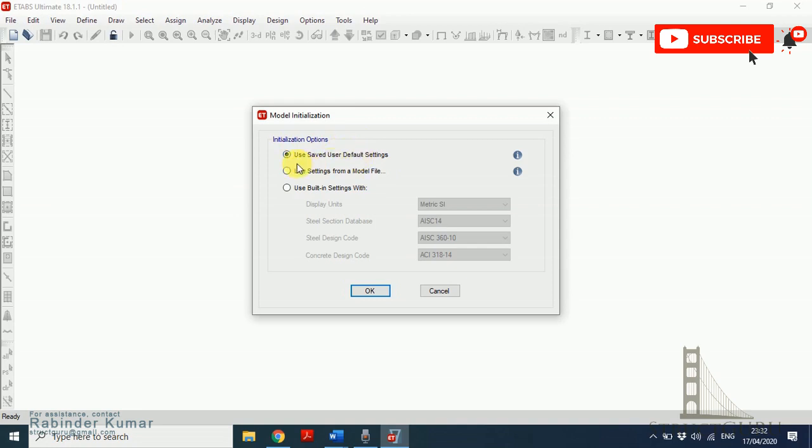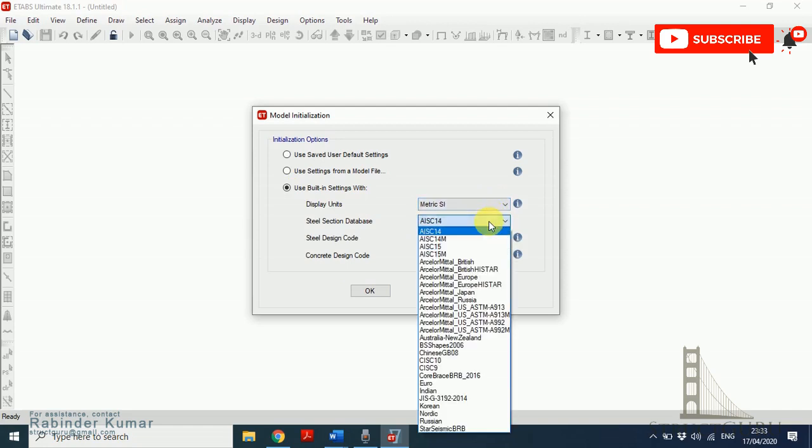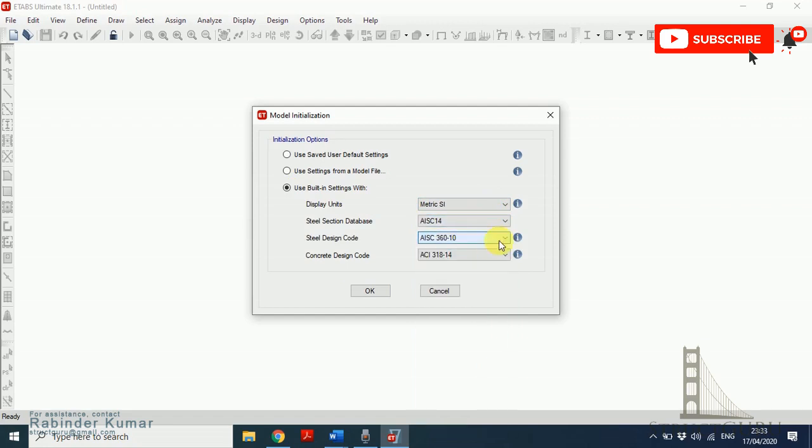If your country requirement is to work with a different set of units, then go to Use Built-in Settings. From there you can choose the different set of units and also the design codes. For our case, I am going to use ACI 318 2014 for the concrete design code. For the steel design code, I will stick to AISC 360. Click OK.